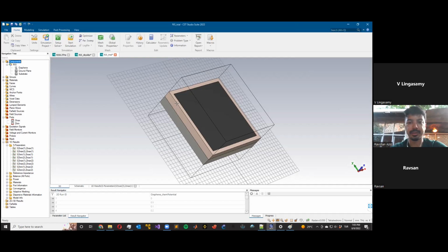For the array of antenna elements, the phase distribution you have to estimate from your algorithm, right? What phase I have to introduce there. Accordingly, according to the phase requirement, you can place unit cells of different sizes. Then you will obviously get that. No problem.